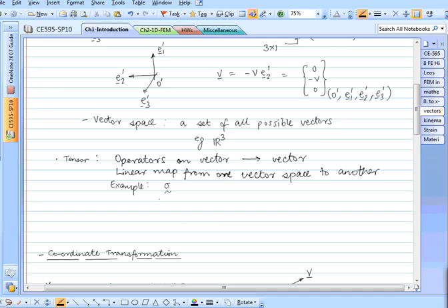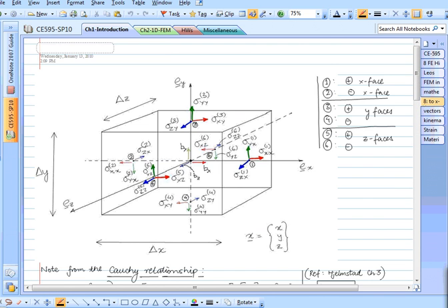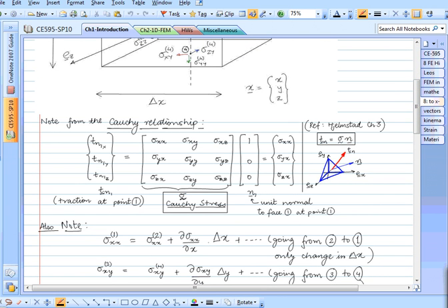Right, right. So the normal vector n, that is the vector that Cauchy stress acts upon, right? So if you go back and take a look at this thing that we were talking about right here, this is the Cauchy relationship. If you take the Cauchy stress and apply it or operate upon this n vector, what you are going to get is a traction vector. It takes the normal vector, operates upon that and gets the traction vector.